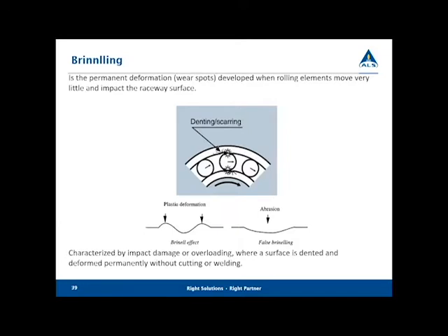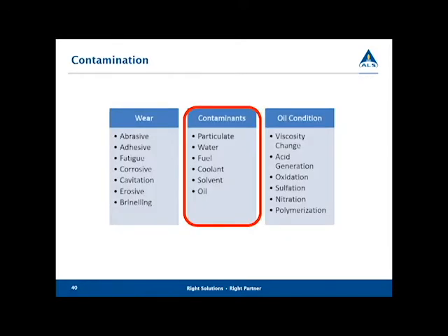False Brinelling occurs if you have something sitting on the shelf and there's vibration. A lot of micro pitting can occur too. That happens too. Now, that's a real quick summation of wear. It's really easy to get our hands around that.